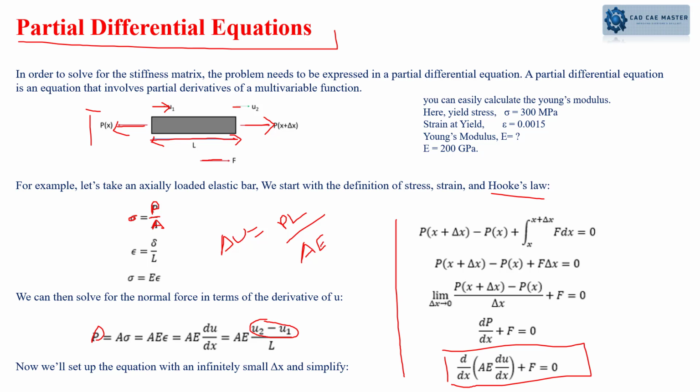Now let's say you have a problem, just imagine, where we have the axial load which is fixed here, and I have applied a certain load here. If you would like to find out the change in length given the original length, we use all these inputs: the load, the total length, area and Young's modulus, and you achieve this.